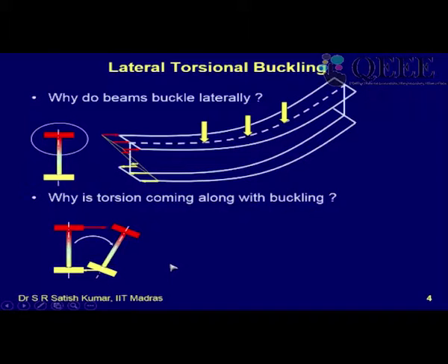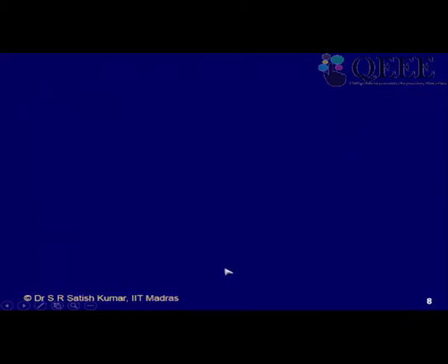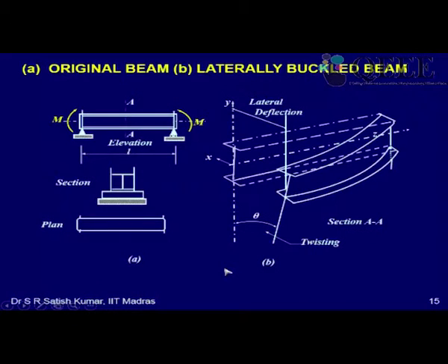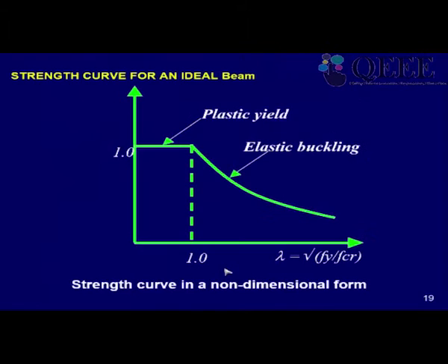And in structural engineering, generally we tend to apply loads on the top of the beam, right? Very rarely, like when you have something called an underslung crane, then you will apply a load at the bottom of the beam. Or if you are having some secondary beams bringing the load, then the load level may be different. But generally the load will be at the top flange. So the effective length for top flange loading will again be different, but then that may be difficult to consider. So what the code says is that you increase the effective length by 20%